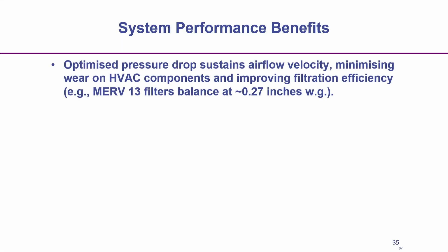And the system performance benefit: you can see an optimized pressure drop sustains airflow velocity, minimizing the wear out of the filter component and improving the filtration efficiency. So, we should always target to keep the pressure drop low.